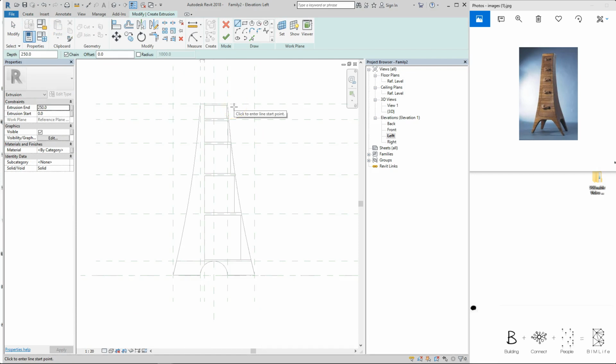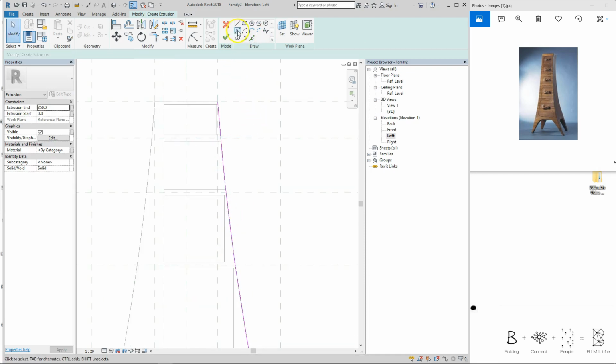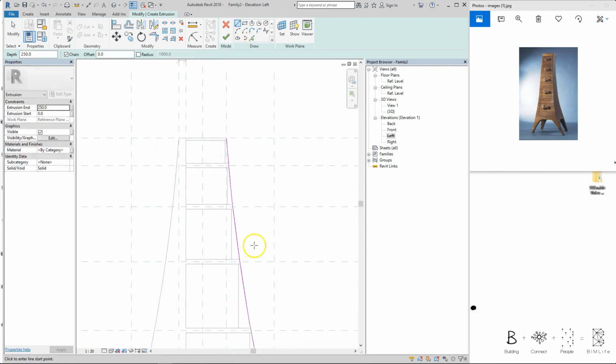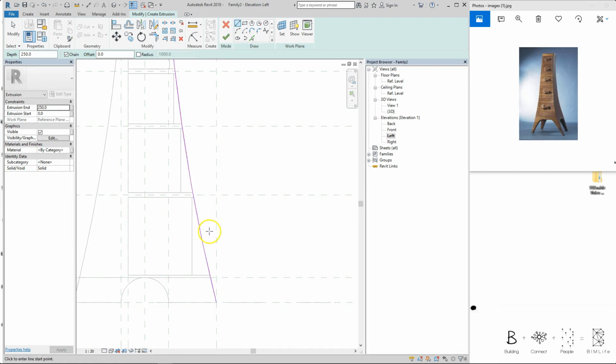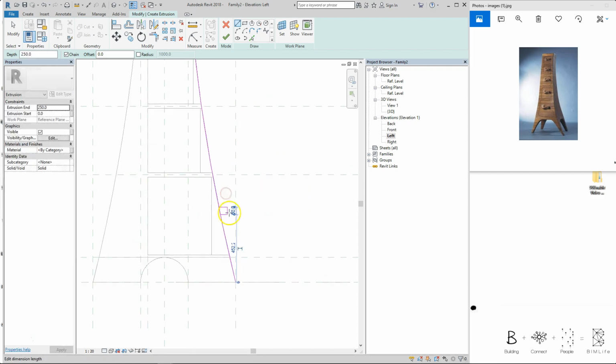So what I'm going to do is use the pick lines command, click on the curvature, click on the lock, and I'll just create the handle from the bottom to the top. I'm just going to draw any lines from anywhere, but I'll keep this at about 50 thickness. Drawing back, trim it.